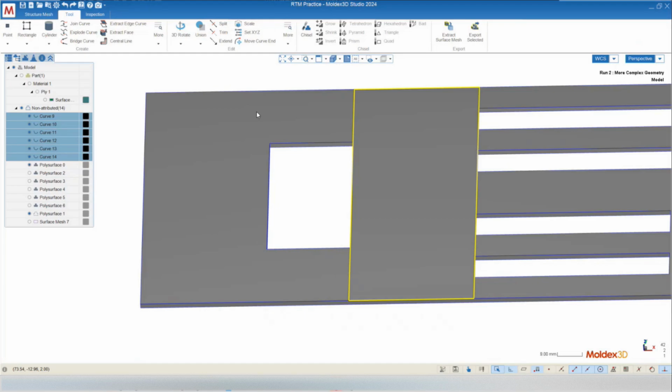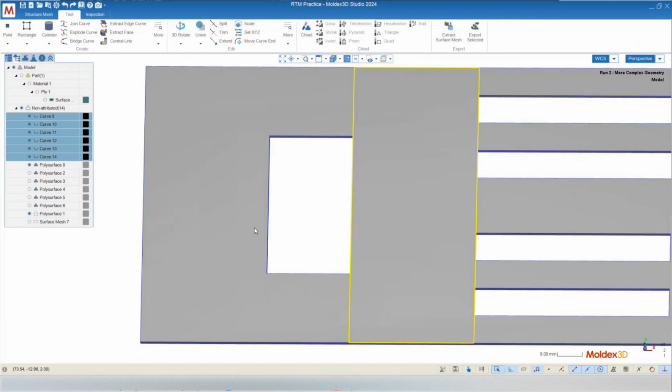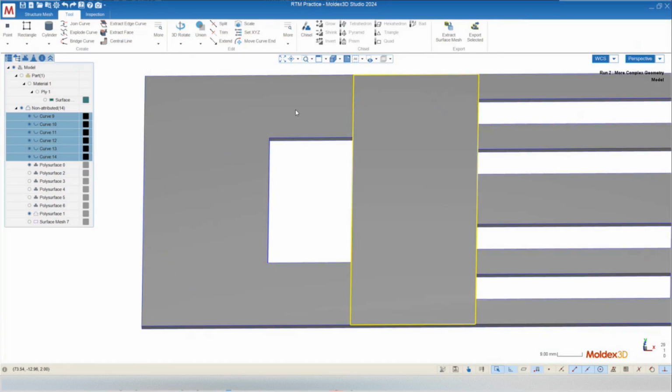And the reason for that is because I have this rectangular cutout that has some nodal array. If you remember, we had 40 nodes on the top and then 7 on the side surface. I need to guarantee that this nodal array matches up. And in order to do that, I have to do this in sections where this section has the same nodal array as what we have connected here. And then this section here has the same nodal array that I have connected here. And then these two corner pieces will just be kind of matching, I guess, to this piece and this piece.